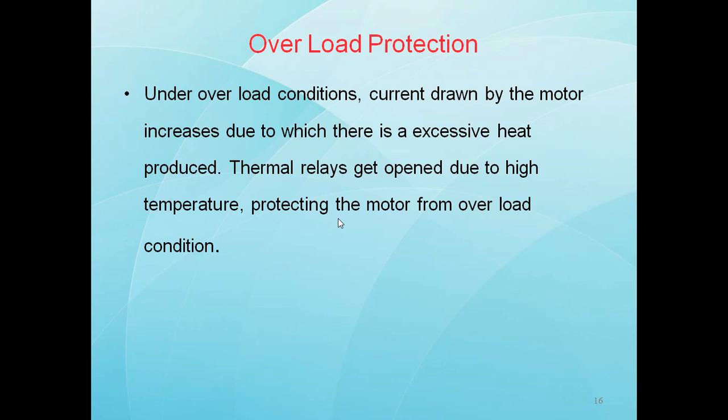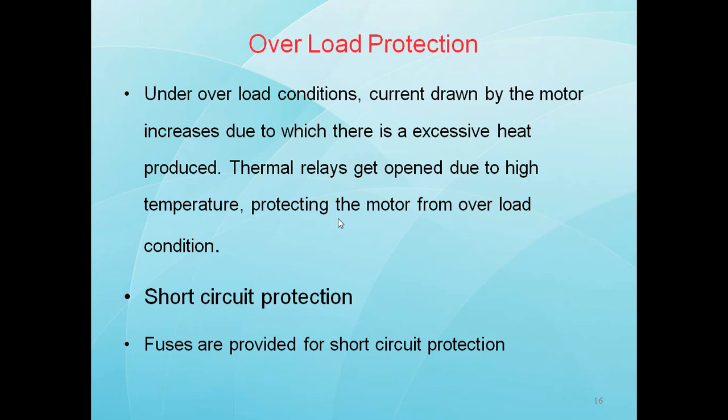I will explain once again. When overload comes, the current drawn by the motor also increases. As this current increases, more heat is produced. Because of this, the thermal relay gets opened due to high temperature and protects the motor from overload. So that is the overload condition.